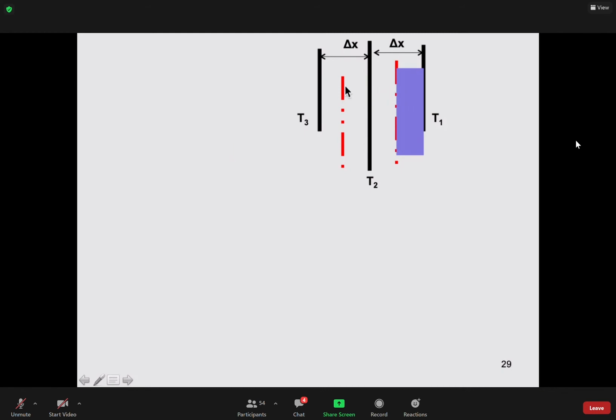Therefore, we add this material. We said this part of the mass here represents node number 2. We assume the temperature here and the temperature here is the same. Therefore, the whole layer here, this thickness of delta X, is represented by one temperature, and this part is represented by another temperature. That's what happens when we change a differential equation into finite difference. Therefore, we can calculate the temperature at node number 1 and node number 2. We cannot calculate it here. We can break it down into smaller layers, but that takes more time to do.